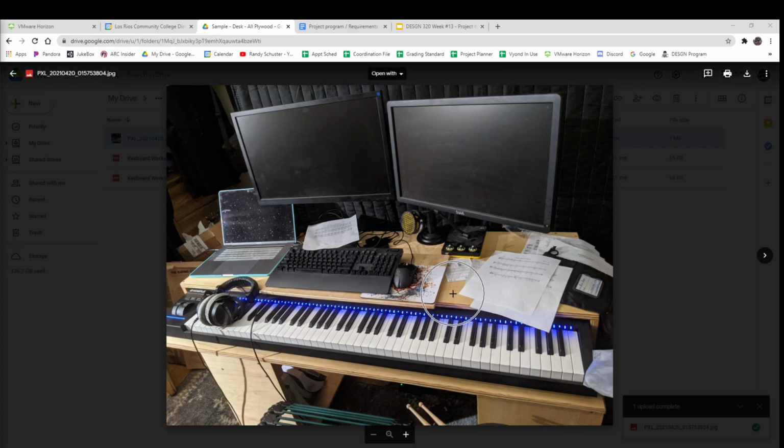So this thing, all of this came out of 1 sheet of plywood, by the way. Everything on here was out of 1 4x8 sheet of plywood, 3/4 inch thick. And we designed this in Inventor so that we could figure out loads and how much it would bend. So if he leans on this point right here and puts 50 pounds load on it, which is a lot, we found out that it would deflect unless we put a little support under there.